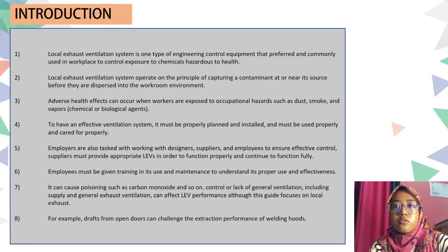Control or lack of general ventilation, including supply and general exhaust ventilation, can affect LEV performance, although this guide focuses on local exhaust. For example, drafts from open doors can challenge the extraction performance of a welding hood.